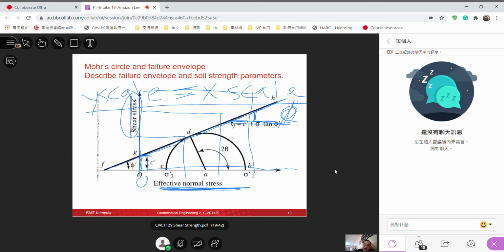，OK，就係咁揾個 Excel 就 plot 出嚟，個 x scale 又唔等於 y scale。如果 Excel 可以 plot，但係你一定要講俾佢聽 x scale 等於 y scale。如果唔係佢就咁 plot 落張圖，x scale 唔等於 y scale，你個 angle of friction 就錯㗎啦，OK？所以記住啦，angle of friction 就喺呢度度出嚟，個 cohesion intercept 就喺呢度度出嚟，再講多一次，唔好嫌我煩。cohesion intercept 呢個位，OK，當 normal stress 係 0 嗰時，喺 origin 度上去呢個就係 cohesion intercept。當 x 同 y scale 一樣，喺呢個 Mohr-Coulomb criteria，呢個 angle 就係 angle of friction，或者叫 internal angle of friction，OK？咁就完成咗我哋呢一個